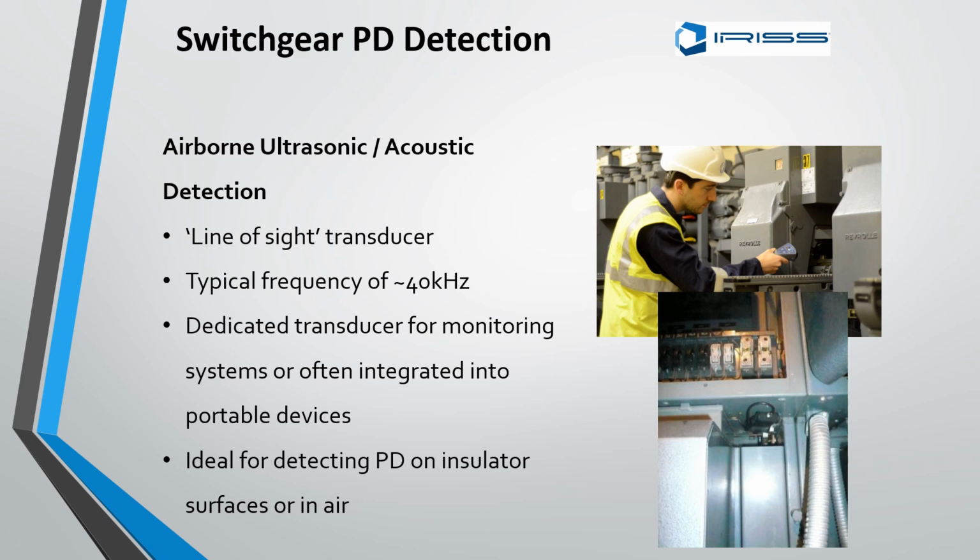So it can be difficult to do on equipment that's completely hermetically sealed up. There's no air vents to listen into. There's no seams around the enclosure. So sometimes we look at also embedding ultrasound listening ports on equipment, or even ultrasound sensors on equipment that we can plug into, especially when it's completely outdoor rated, hermetically sealed equipment. So you're in this instance looking more for those airborne ultrasound signatures that come from the surface events, arcing, tracking,